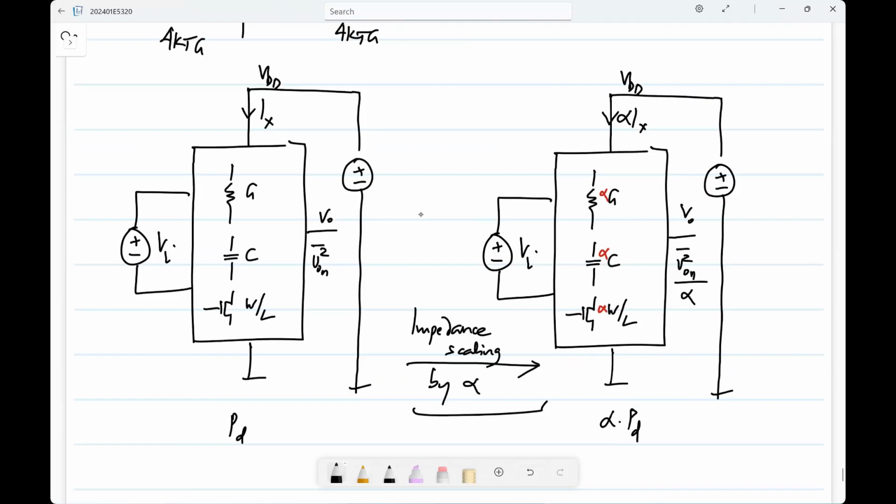You can reduce its power dissipation. Okay. So you can go the other way also. It's not that you only go towards reducing noise. The goal will never be to increase noise, but you may allow an increase in noise because you want to reduce the power dissipation. Okay. So both are done. This is again some standard design tool. Okay. Of course, if none of this works, then you may have to go and think and invent new circuits which will have lesser noise or something. Any questions here on impedance scaling?